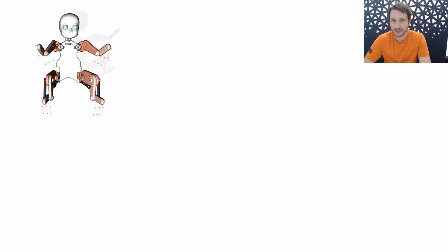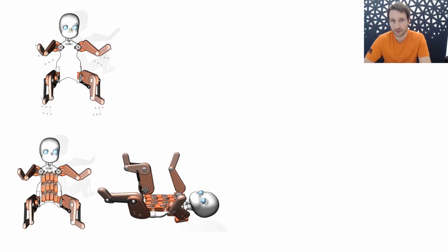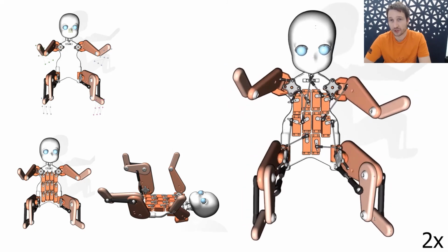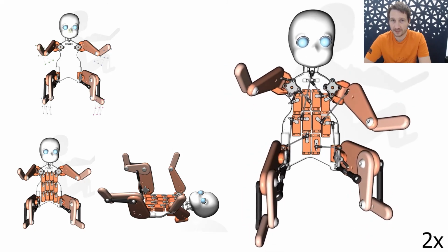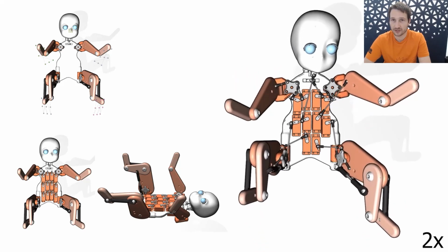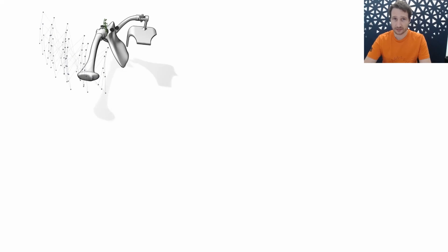First, let's start with a baby model with 10 degrees of freedom and 24 possible motor positions to choose from. The motors are stacked in 2 overlapping layers, each with 12 motors, to accommodate for multiple motors intersecting. We just don't create a child node in the tree if the parent and child node would intersect with each other. For this result, we created a shoulder mechanism with 4 degrees of freedom and 7 motors and 3 via points.